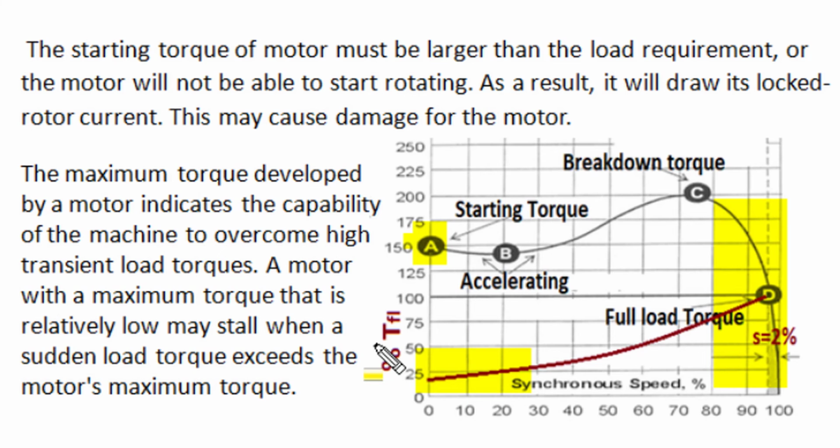But if load is a heavy duty start type of load, then we have to use either class C or class D type of motor so as to ensure safe and smooth starting. Now at the time of starting, we also have to consider the starting current drawn by the motor, and NEMA standard B design motors are designed in such a way that with normal voltage starting they draw 6.4 times full load current, and with reduced voltage starting such as star delta starter, when the line current becomes 1/3 of normal full voltage starting current, that current becomes just 2 times of full load current.